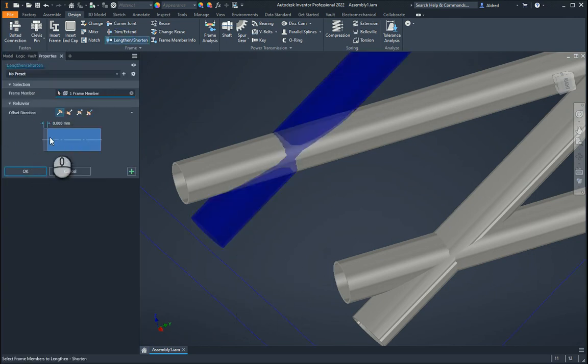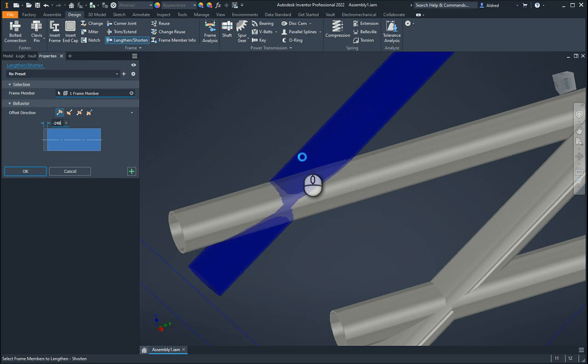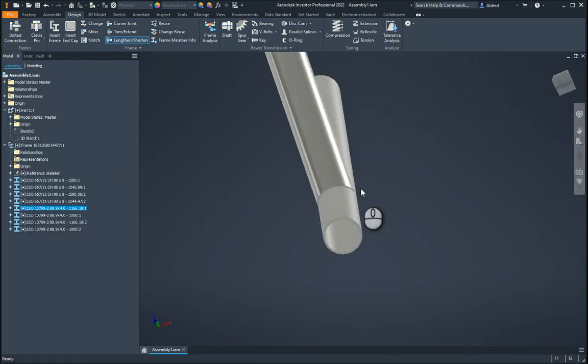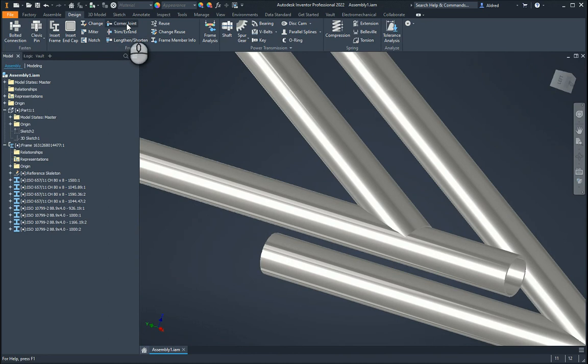So what I would probably do over here is say, right, let's lengthen or shorten it. Let's see, what is it by? I don't know what this is. It's a 50. How much does it shorten it by? Okay, so it's actually added it. Let's go minus 50. Okay, let's go minus 500. Okay, really should be minus 250. Okay, minus 240. Okay, let's do something like that. So there we go. There's obviously interference over there, and this is when you can do your notching.